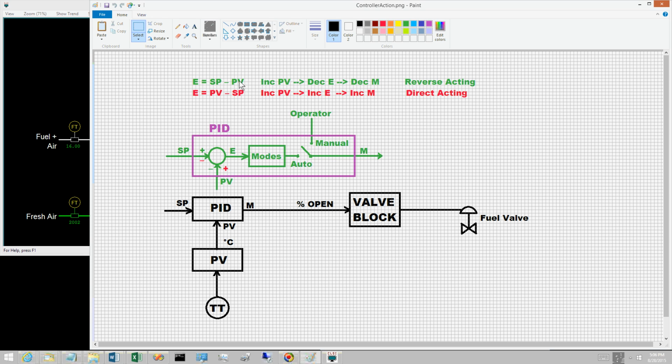By disassembling the hardware. How do digital controls implement direct and reverse action? Reversing the inputs to the comparator is one option, but in software other approaches are possible. Suppliers rarely provide such details, and from an application's perspective, how direct and reverse action is implemented is immaterial.